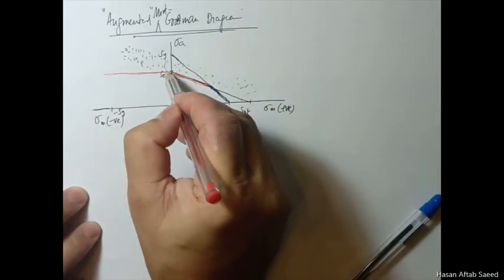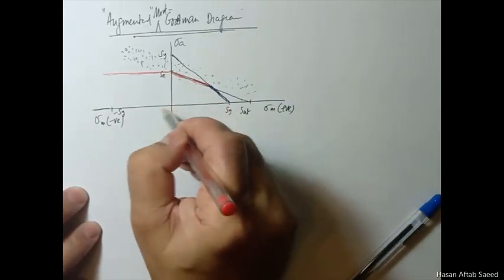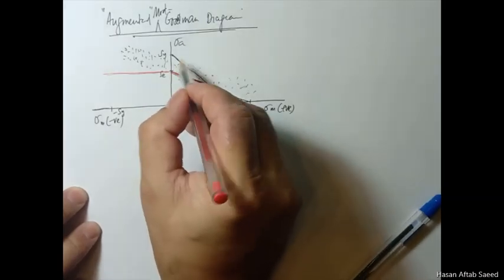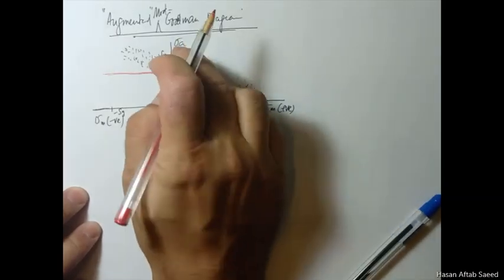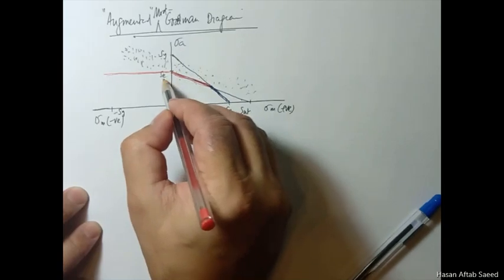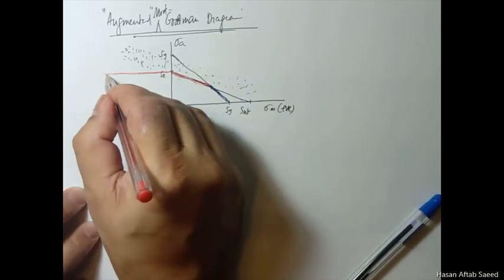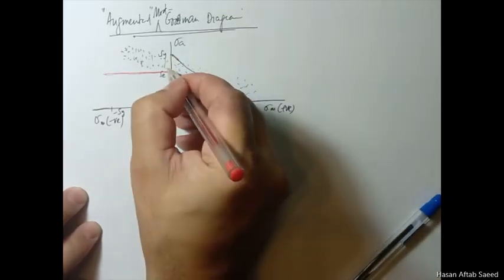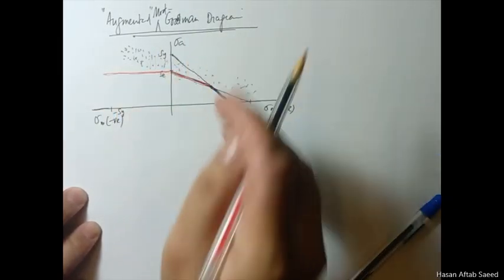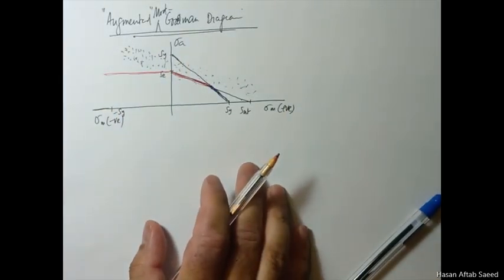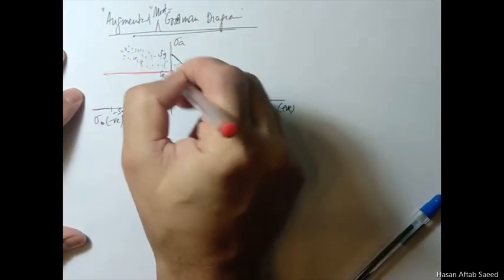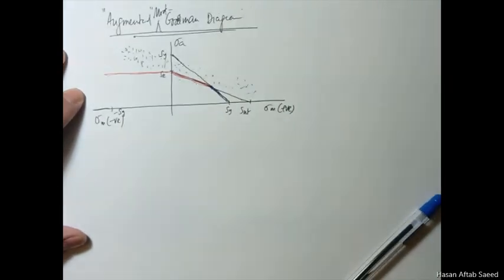That is, if you have a mean stress in the negative, then you can apply the amplitude component of SE in this whole domain, and it should be all right. We could have even increased this here, but we are making sure that it's a conservative design, and it makes life easier for us. So this is your negative region, but again you have to be careful.